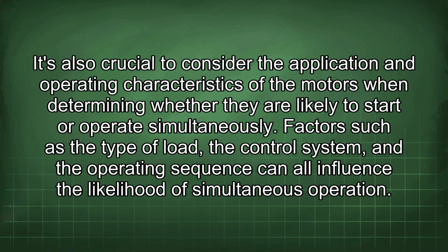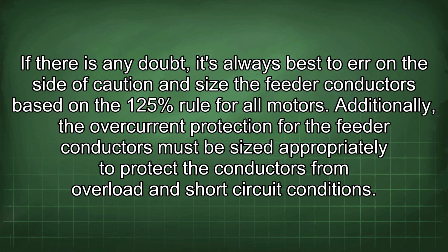It's also crucial to consider the application and operating characteristics of the motors when determining whether they are likely to start or operate simultaneously. Factors such as the type of load, the control system, and the operating sequence can all influence the likelihood of simultaneous operation. If there is any doubt, it's always best to err on the side of caution and size the feeder conductors based on the 125% rule for all motors.